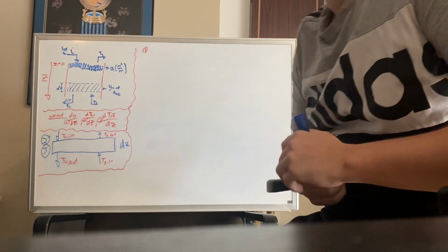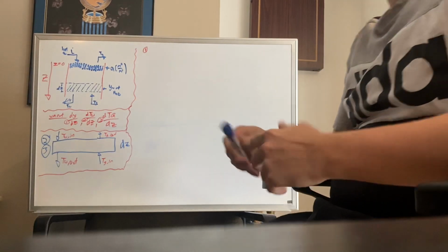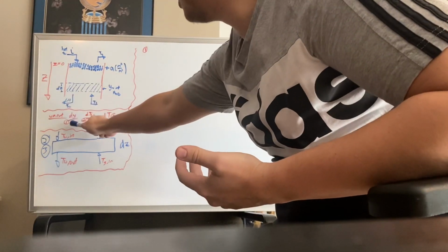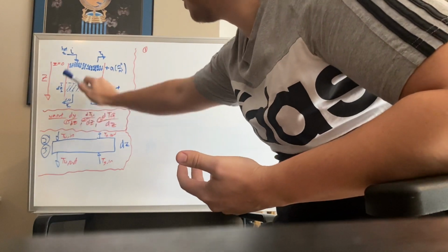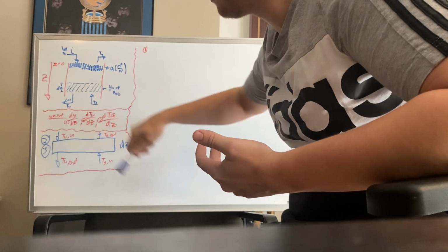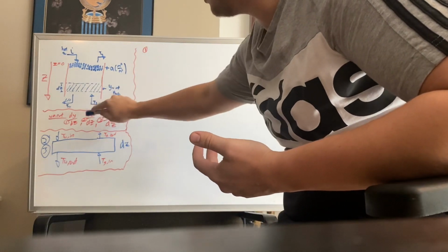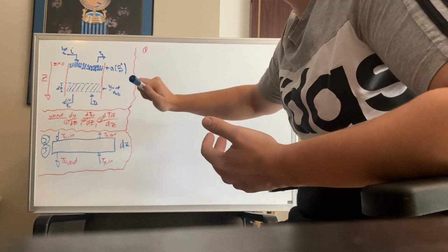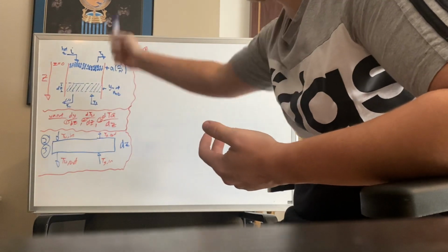What we really want to do in this whole part of the exam is find the rate of change of the mole fraction of water with respect to the change in distance of the cooling tower, the rate of change of the temperature of the water as it goes down the cooling tower, and the rate of change of the temperature of the gas as it goes up the cooling tower.